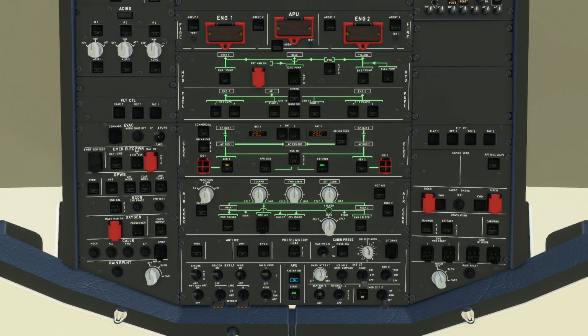I turned off one of my engines, but it's the engines that generate power for the aircraft. So if the engines are off, you have to use another means to get power. Now, you can see up here there is external power which is available, and you can turn that on so you get power from a generator.